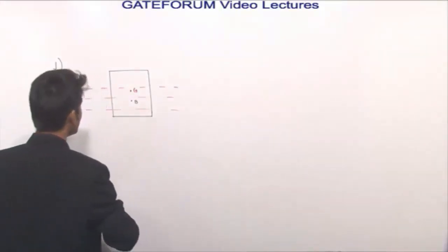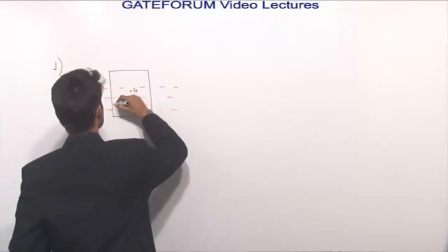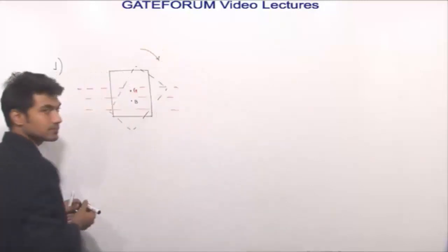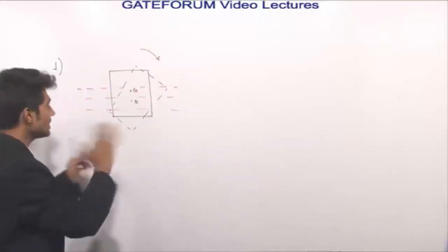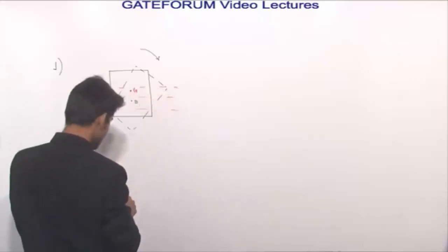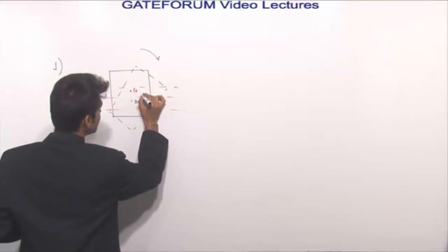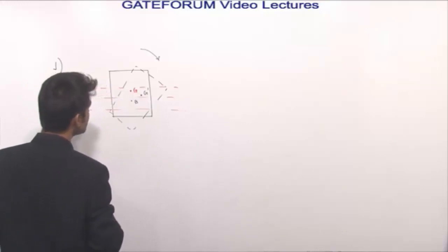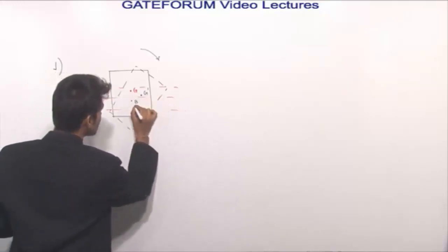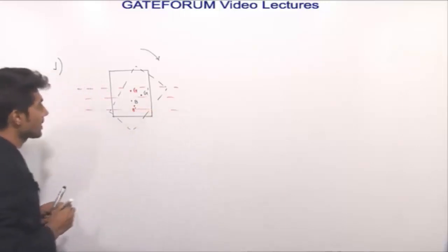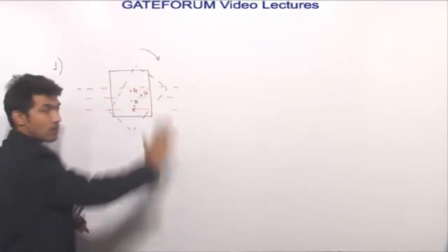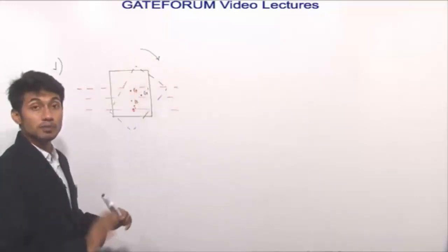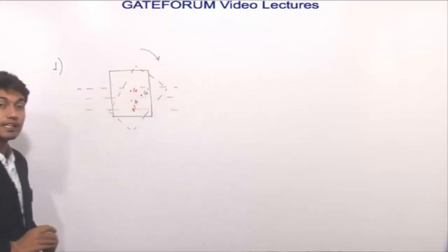So what we can do is, we can tilt this object in the water. We have tilted this object in clockwise direction. Now we have disturbed it and it is released. Now when it is tilted in this particular direction, the center of gravity will come over here, it is G dash, and center of buoyancy will remain somewhere over here, we can write it as B dash. Now if we have disturbed this object, to get stability, a reverse direction or opposite direction torque should be there, so that the body will again go to its initial equilibrium position.